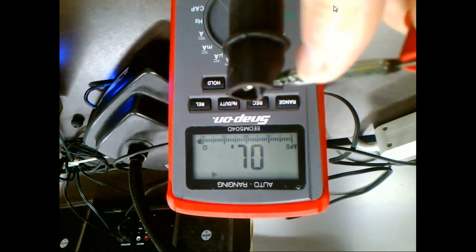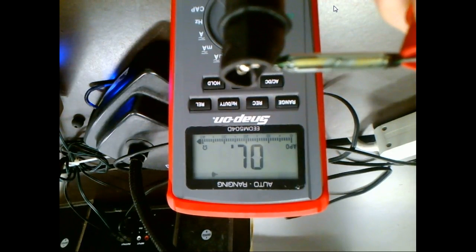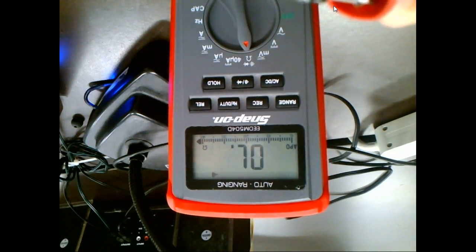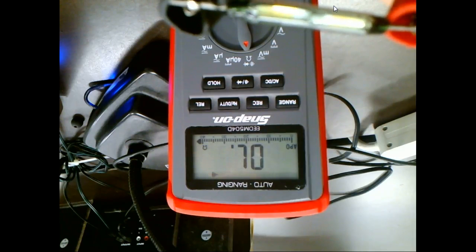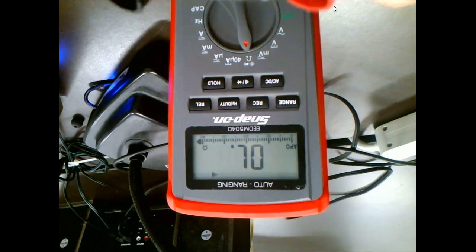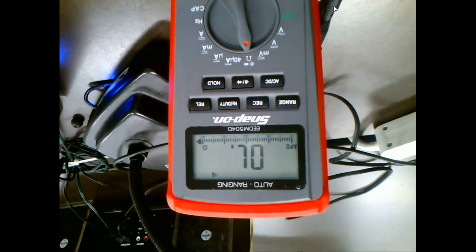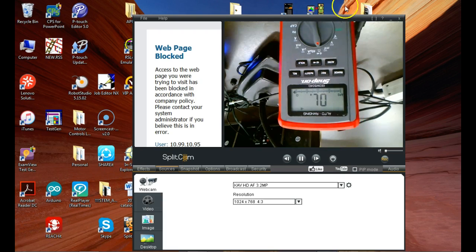Something could happen up here where it wasn't made exactly right, and one of these arms could break off or something like that. Or they could get shocked and they get bent out too far, so they don't get enough motion to do what? Make contact. So these are electromechanical devices. So that's the biggest problem. But what advantage does it have? Cheap. The cost. They're cheaper than a solid state, or one we'll look at next, which is a Hall effect.